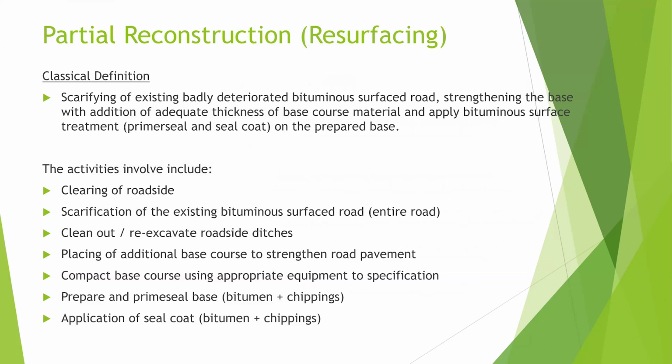is partial reconstruction, meaning that if you do not do resealing and you begin to have more defects showing up, and resealing is not applicable, then the next periodic activity that must be considered is partial reconstruction. We used to call it resurfacing.